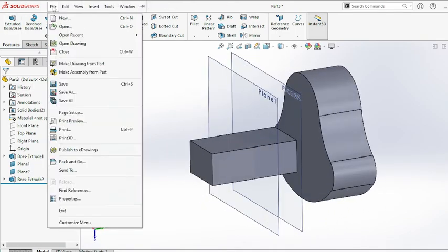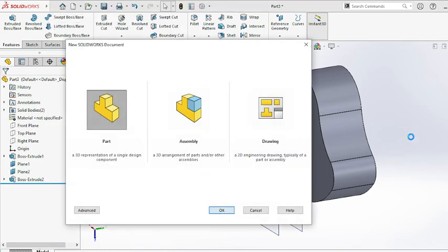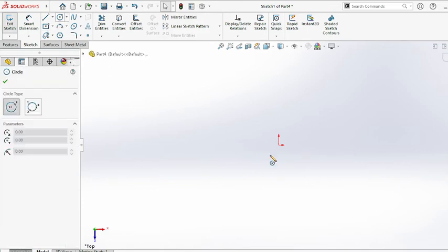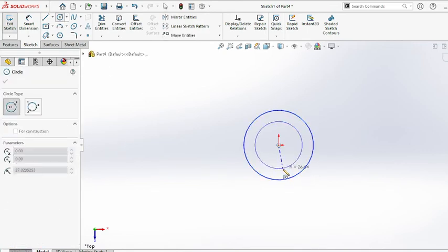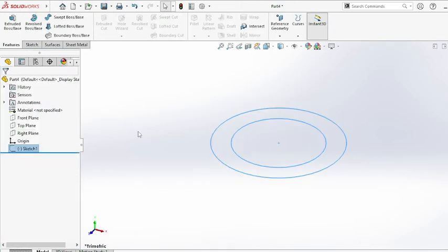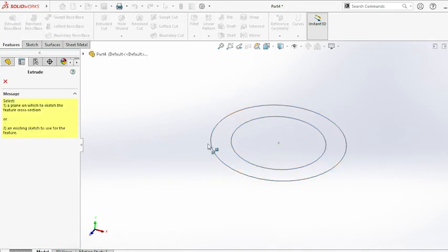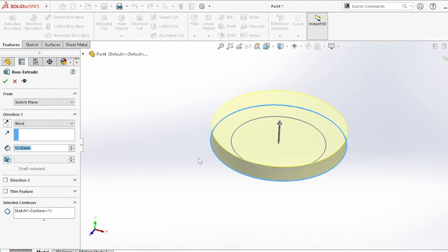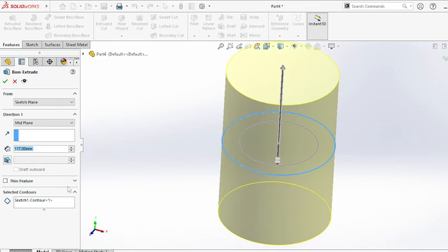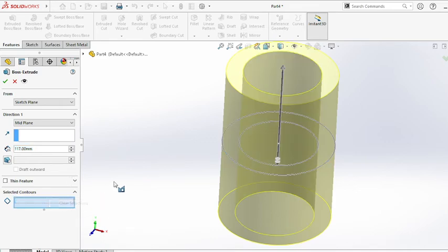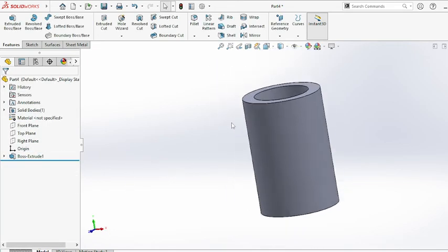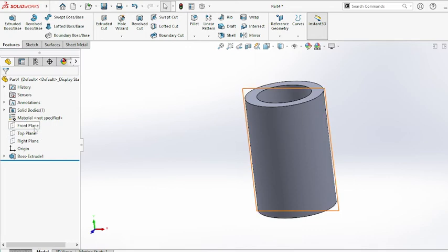Okay, in total these are the options, but I am discussing one more example. Mostly used is up to next surface, which is very important. You can use the extrude command. Here I am selecting only one circle, but I drew two circles, and the other is not selected. At that time you can select another one also. Here, right click, clear selection, and two will be selected. That is the use. Okay.